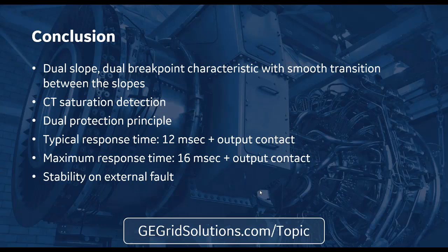And going back to your point, yes, if I was doing any type of bus protection on a greenfield project, definitely I would go with a low impedance differential. And most utilities have gone that way. Anytime they're doing any type of new installation or new work, they will go to a low impedance scheme. High impedance schemes are still out there. They're still specified.